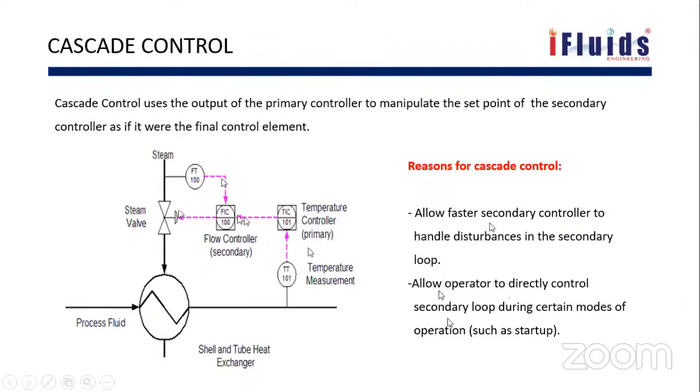So this is how cascade control works, nothing but cascading the effect to the secondary controller. Directly giving the temperature signal to this steam valve will only disturb the process, because once the temperature reduces, it will open or close, steam has to flow in, it has to sense, and then again it will keep on adjusting. It exactly doesn't know how much steam has to be given.